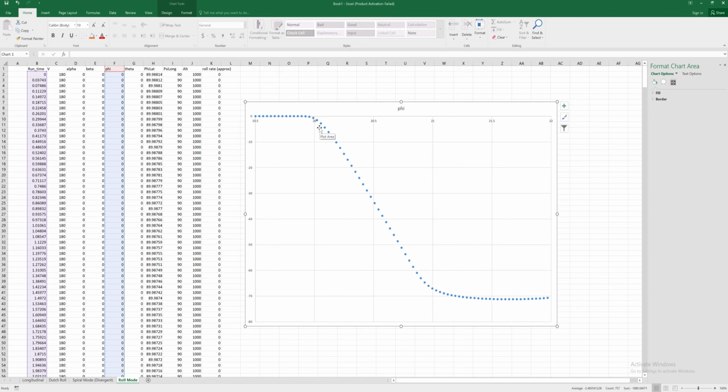And usually, the roll mode isn't really a problem on most aircraft. Now, when I worked at Scaled, I worked on the Stratolaunch aircraft, and on that aircraft we were concerned about the roll mode, because it had so much inertia about the x-axis. We wanted to make sure that the ailerons were large enough so that when the pilot deflected the ailerons, the aircraft responded rapidly, or at least rapidly enough for that pilot to maintain control of the aircraft. And so our transients were much longer because it took a while for that aircraft to ramp up to a steady rolling rate, compared to a smaller aircraft that would ramp up much more quickly because they don't have nearly as much inertia about the x-axis.